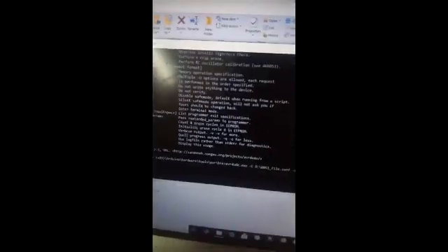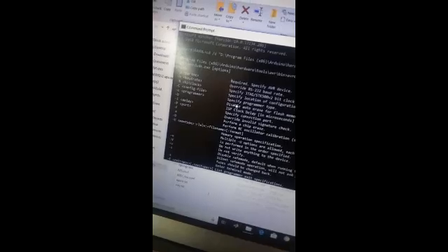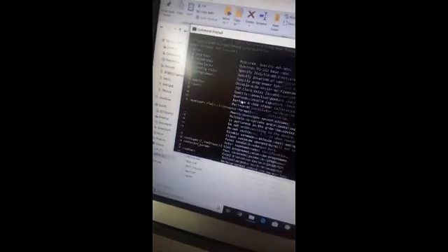Now if we look for other file, there is small c AVR ISP. The small c stands for programmer, to specify programmer type. We are using Arduino as ISP, so we have chosen AVR ISP, and the b is bitrate. Small p is the part number, you can see it from there.